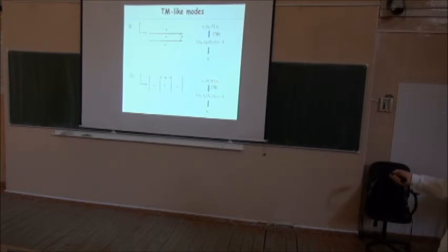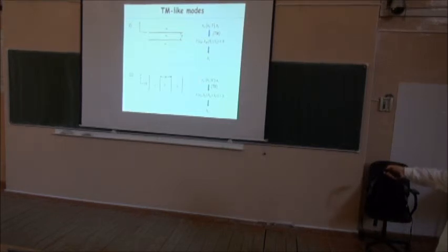So that calls for the TE case. So in this case, the structure of my waveguide is actually a symmetric waveguide with the refractive index of the substrate on both sides, and I have an effective index and a width W there.